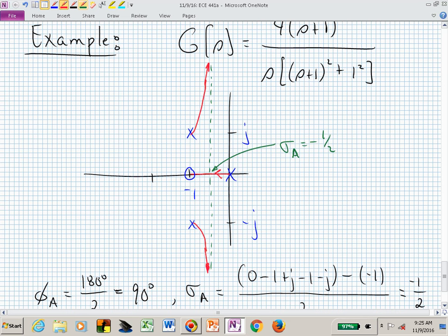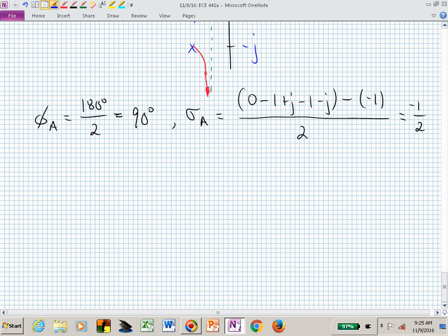Now, suppose that somebody gives you design specifications and they've consolidated those into simply saying, I want my closed loop poles or a set of closed loop poles at a particular point. Suppose that they say the design specs that I want to accomplish would be that I want my root locus to pass through S sub delta equal to -2 plus and minus j2.